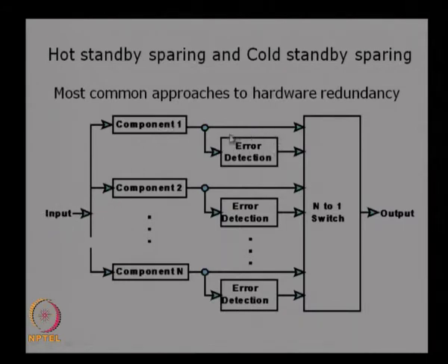And then there is an error detection function over here. The role of the error detection component is basically to look at the output from this component and compare it with a predefined or set value. This algorithm will have a predefined value, like the expected pressure, expected temperature, or expected time of processing, and it will check whether the output from component 1 is the same or not. If it is not the same, then an error will be declared.